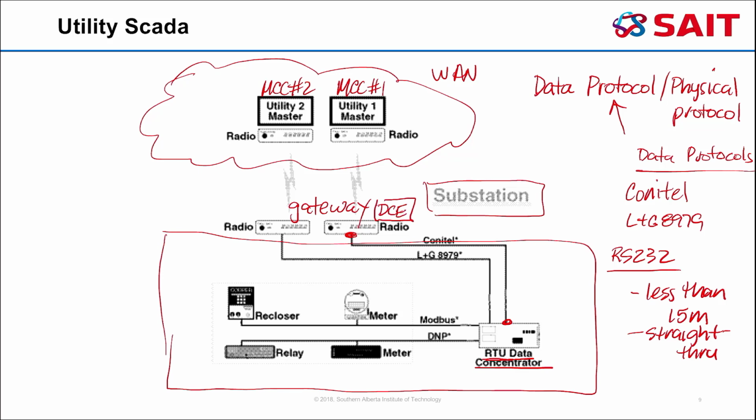Wireless radio is the one that takes the signal from the terminal, highs and lows, which we know is the same for all terminals, and changes it to a signal appropriate for the transmission medium, which in this case is radio. It would have to change it to an RF carrier to send out as a wireless connection.